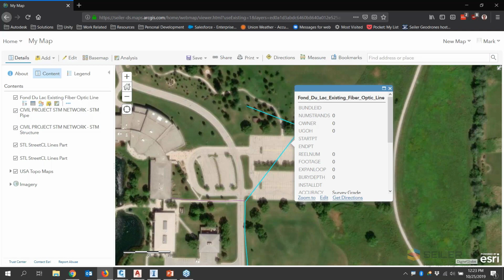You can at least bring it in as feature line data, which is kind of a universal line. Bring it in as a feature line, make any kind of changes you want, convert it to a polyline if you want to, and then convert it back to a feature line. You can write that data back out. So at least you can have the line work and then convert it to pressure network parts if you want to from that point. So that's the one downside that I have right now. Other than that, I really haven't had a problem for the most part.